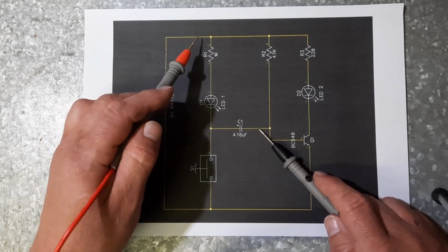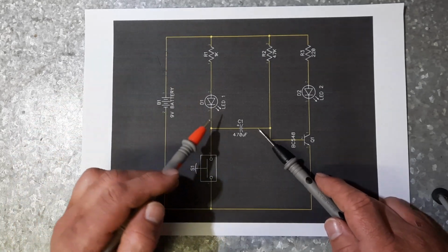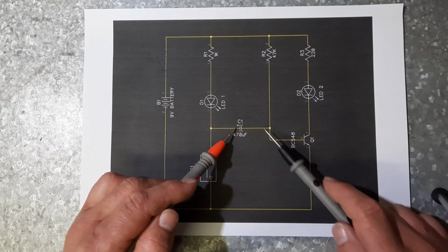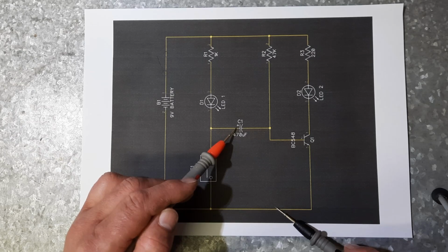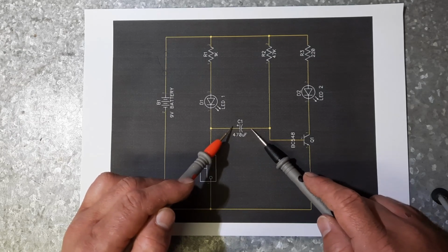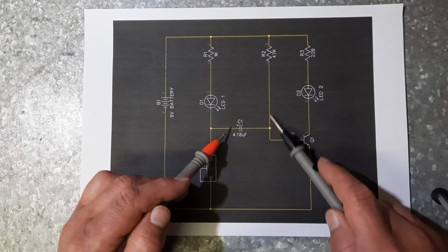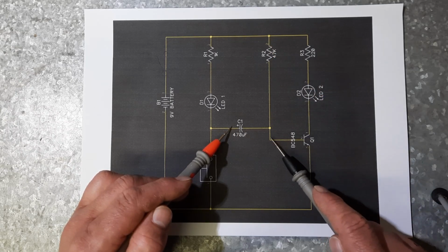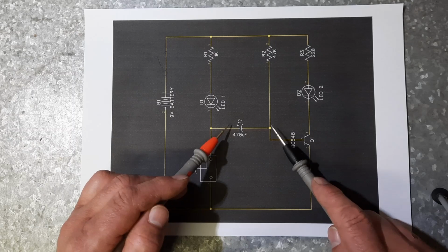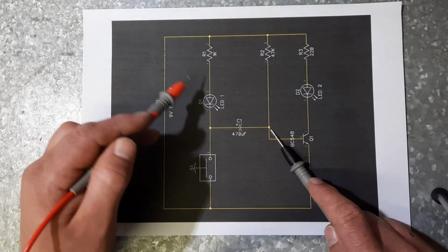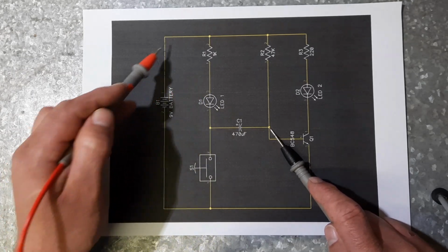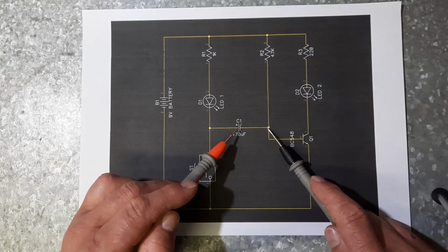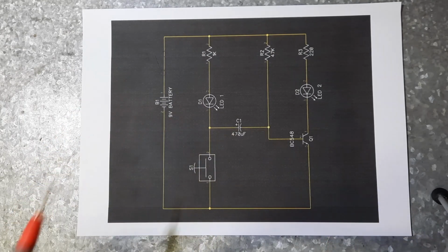8.3 plus 0.7 equals 9. So if the negative plate of this capacitor was at 0, not 0.7, then this would charge to 9. But that's not going to happen, because we know there's a 1 volt drop here and the second one from here to here. So this is at 0.7 of a volt. Without this LED here, this cap through R1 would charge to 8.3 volts.